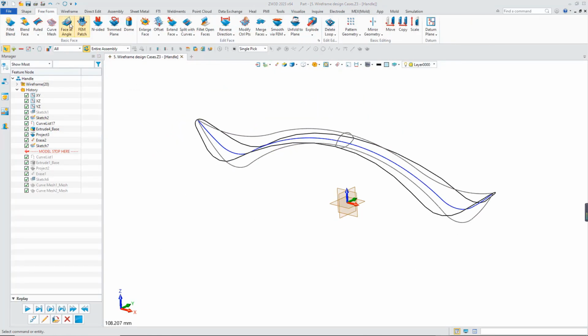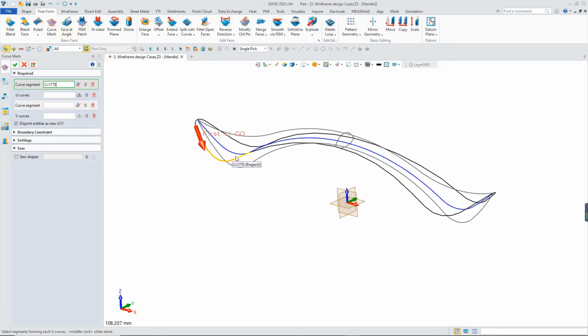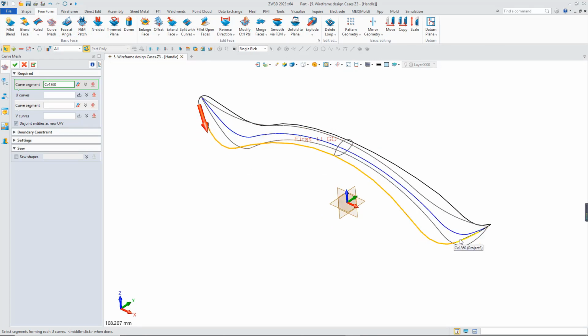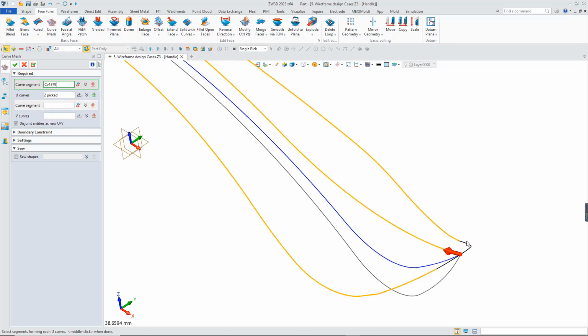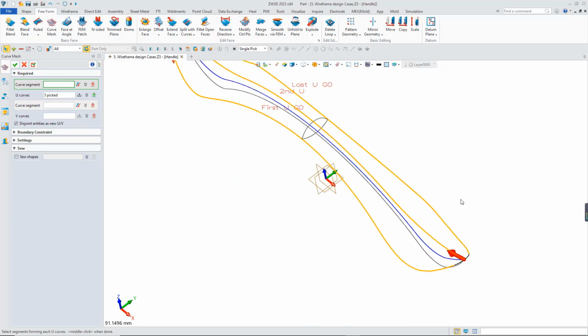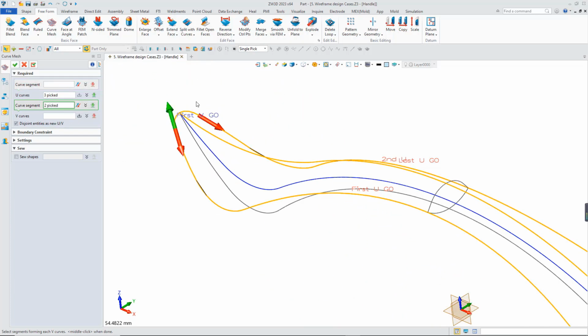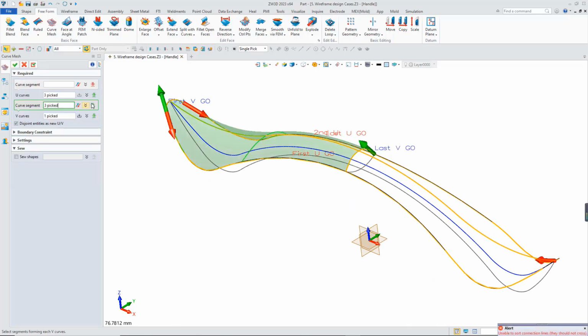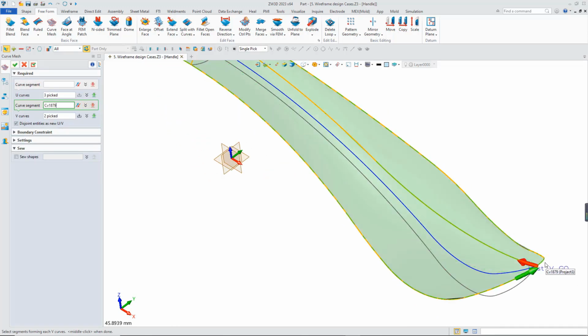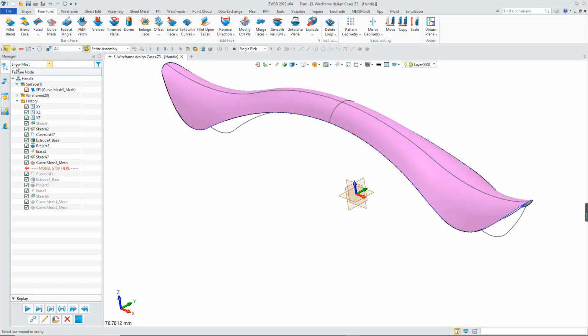Finally, we could use the freeform function to finish the surface modeling. We create the top curve mesh first. Define the U curves. And then define the V curves. For more details regarding curve mesh function, you can study the freeform tutorial, which will be the next.